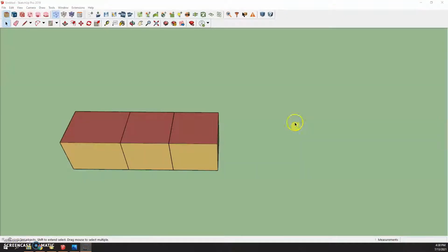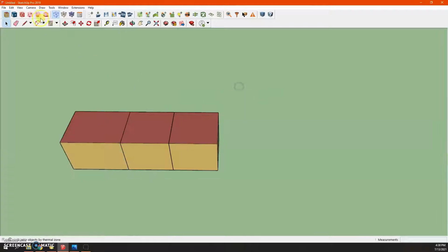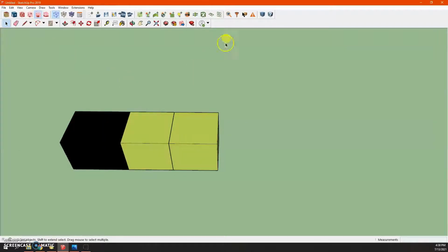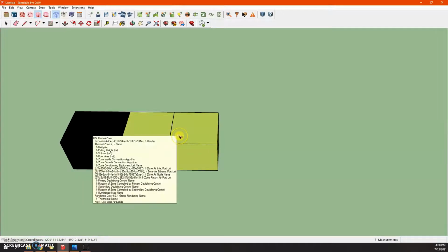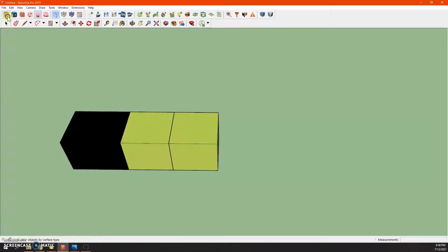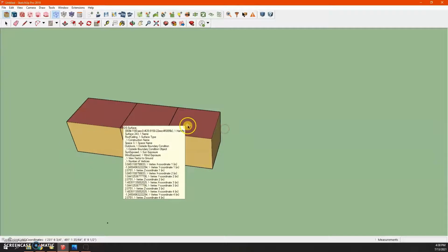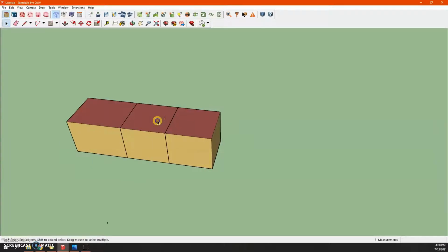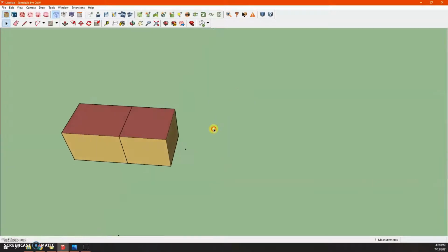So jumping right into another extension, we will learn how to edit the thermal zones of spaces. So as you can see here, we have two spaces corresponding to two thermal zones, thermal zone 1 and 2. And here, we want to actually split thermal zone 2 into two different spaces, so then we can assign it thermal zone 2 and thermal zone 3. So to do that, I'll start by using the old-fashioned way. I will delete half of the space. As you can see, it's divided into two rooms, so that was fairly simple.